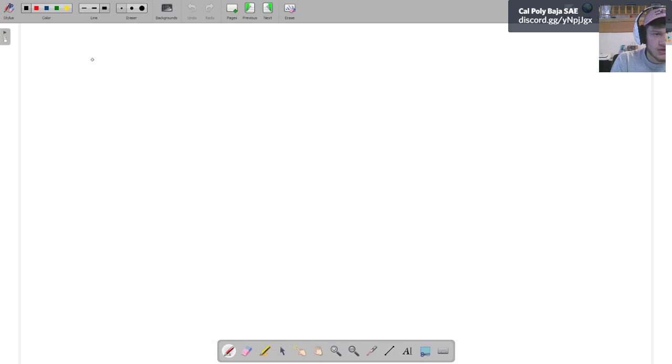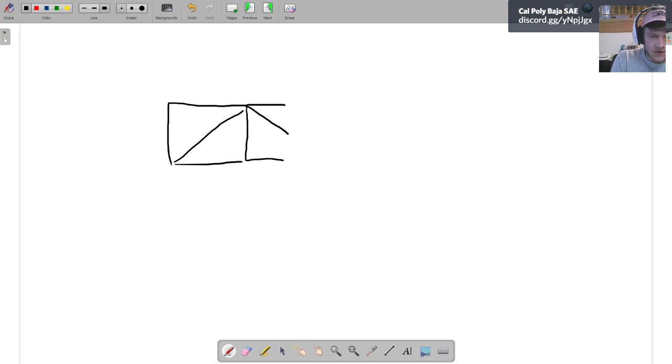So let's jump to a clean page here. I now have a problem that looks like this. Something like that. I've still got all the forces that are acting upon this body like this. There was a slider there. But I now have some amount of reaction, stuff that happened over here that I need to figure out what to do with. And I can use the fact that these are all 2 force members to place my unknown reactions.